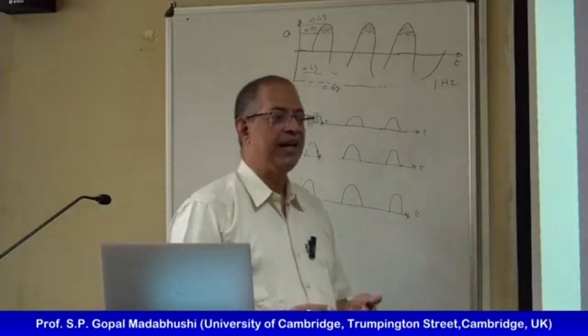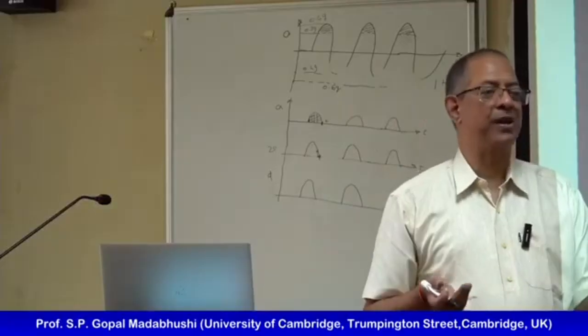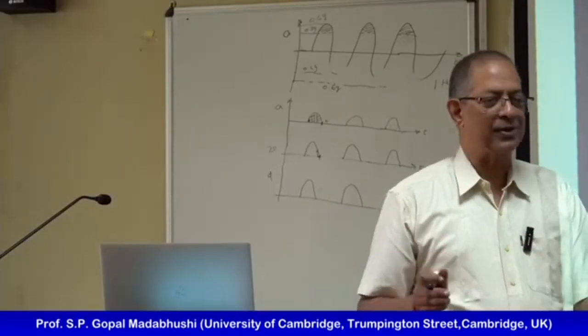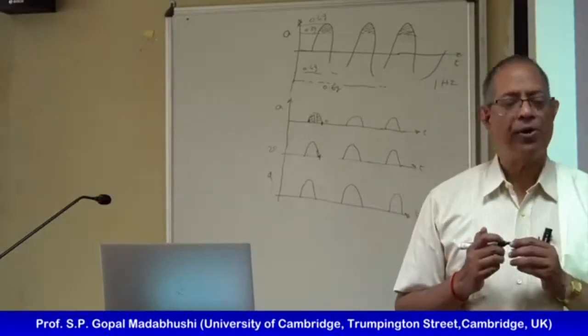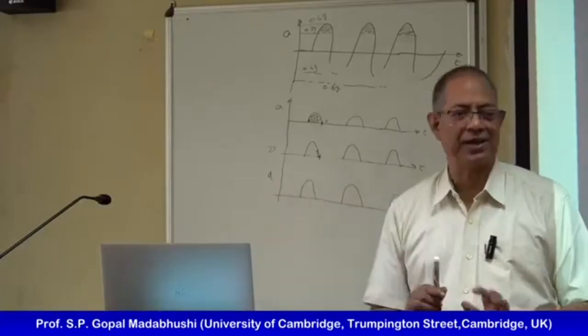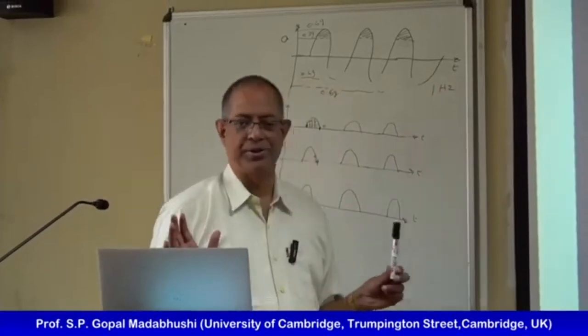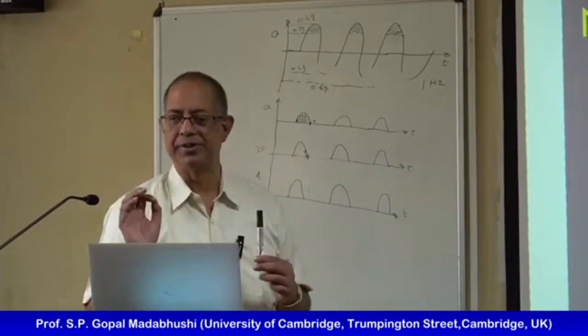It's like stopping distance for a car. The stopping distance you calculate not based on acceleration or the braking force, but based on velocity coming to 0. It's the same thing here. So a lot of people who do Newmark calculation actually don't understand this and make that mistake. Oh, my acceleration stops, it's 0, therefore my body should stop. No, it will continue until velocity comes to 0.